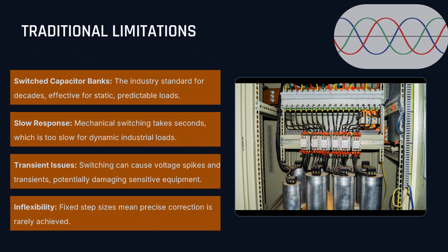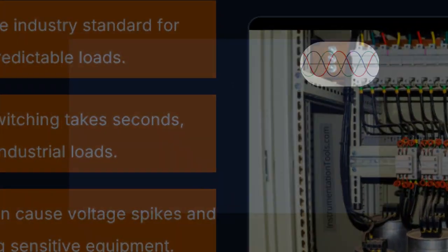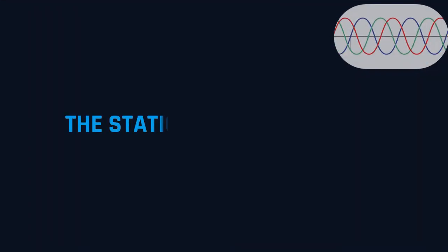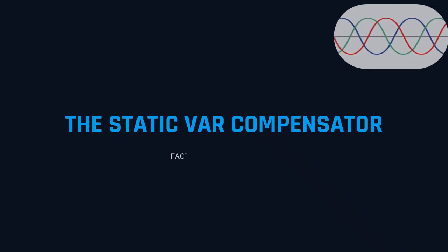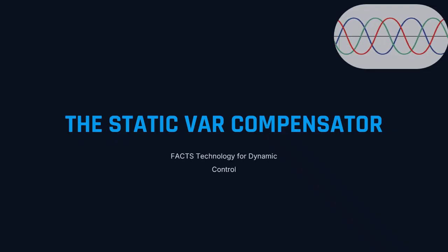The Static VAR Compensator. The solution lies in power electronics. The Static VAR Compensator, or SVC, is a key piece of FACTS technology, flexible AC transmission systems. SVCs leverage solid-state components, specifically thyristors, to achieve continuous, high-speed reactive power control. This dynamic capability is what differentiates it from its traditional predecessors.